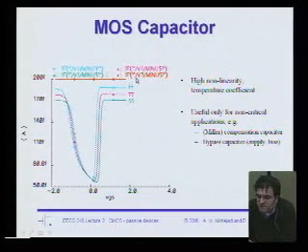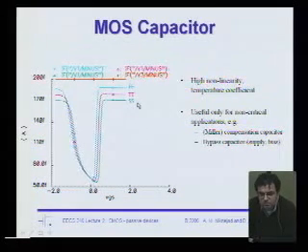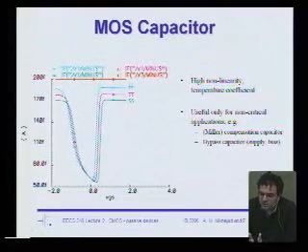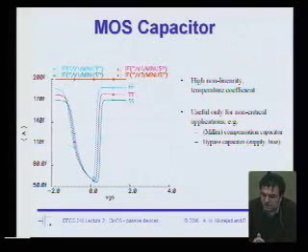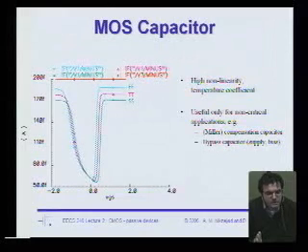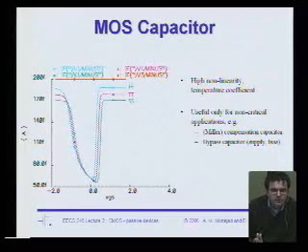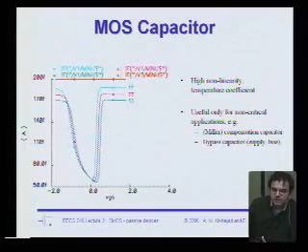Another thing to notice here is that the capacitance varies quite a bit with process. So the model that you have available for this course has process corners. SS would be a slow process, TT would be a typical process, and FF would be fast. Okay? And so the notation is that typical is like your average transistor, right? And your fast transistor and your slow transistor are kind of your, let's say, 6 sigma or 5 sigma, or whatever the process is specified. Those are the most extreme transistors that you would expect to get.